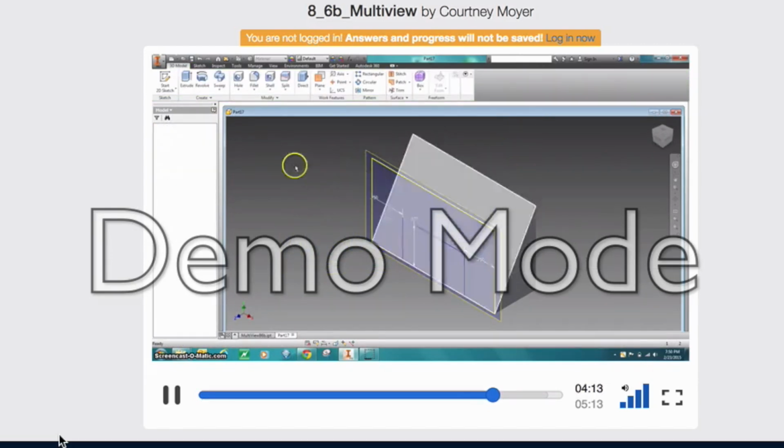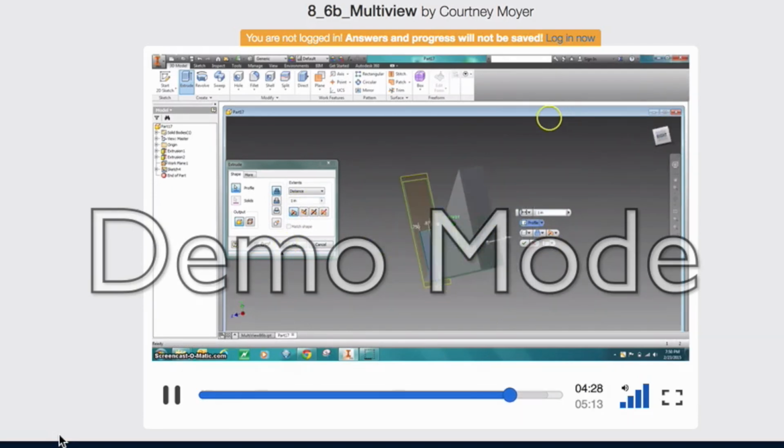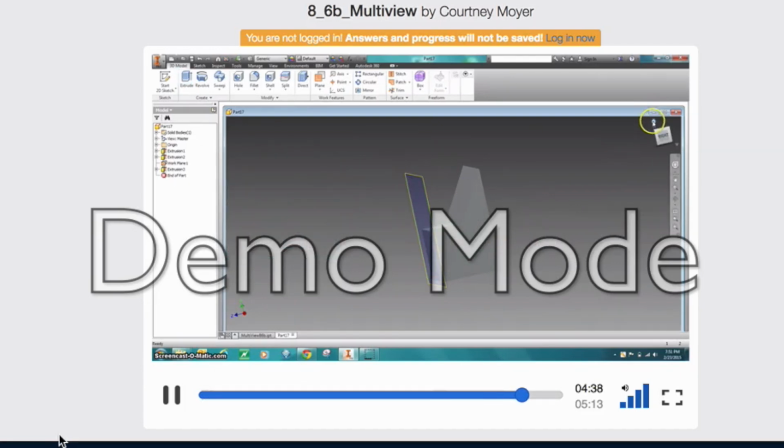I can finish the sketch, and I'm going to extrude from the plane straight ahead into what I needed there. As you can see, it's going into the piece, and as long as it's going in there far enough, I really don't even have to go in. You can almost see it's going in the whole full. If I take that in about 0.75, that's going to be good.